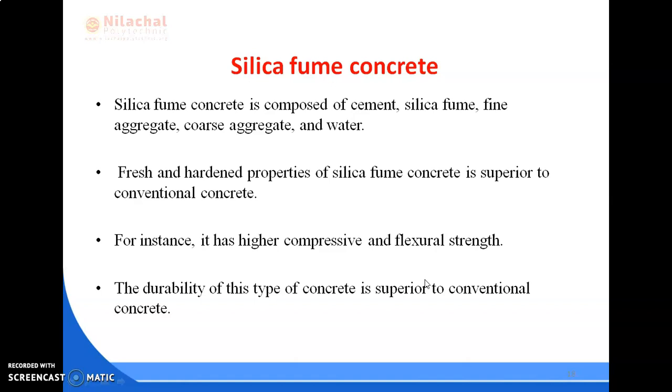And it is generally more efficient in concretes having high water cement ratio. That means 1 kg of silica fume can replace 3 to 4 kg of cement in concrete without changing the compressive strength of concrete. Again, ultra high strength concrete is possible with silica fume additives.